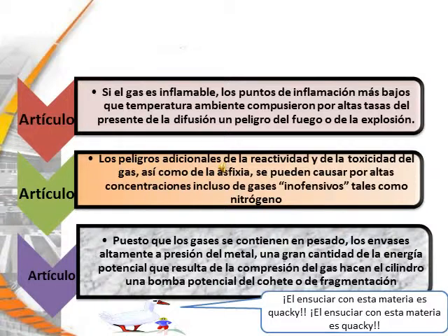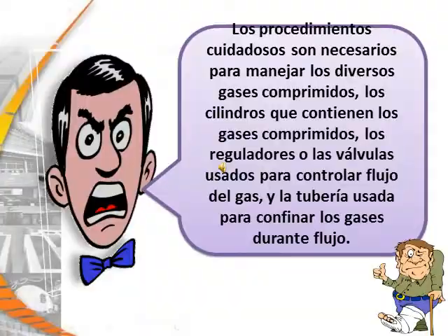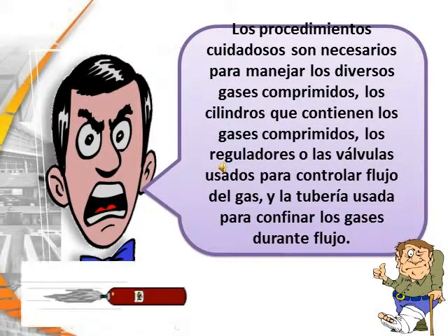Since the gas is contained in heavy, high-pressure metal cylinders, the large amount of potential energy resulting from the compression of the gas makes the cylinder a potential rocket or fragmentation bomb. Careful procedure is required.